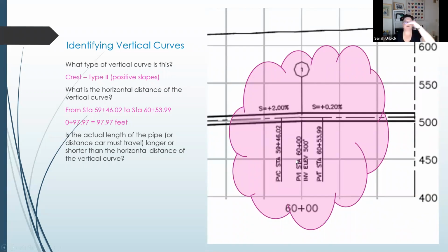Absolutely, it is longer, okay? We're not talking very long, we're not talking very steep slopes, so probably not a whole heck of a lot longer. But basically what we were looking at with the length of our arc and the length of our chord, that's kind of what we're doing here, only in a profile view instead of a plan view. Okay.